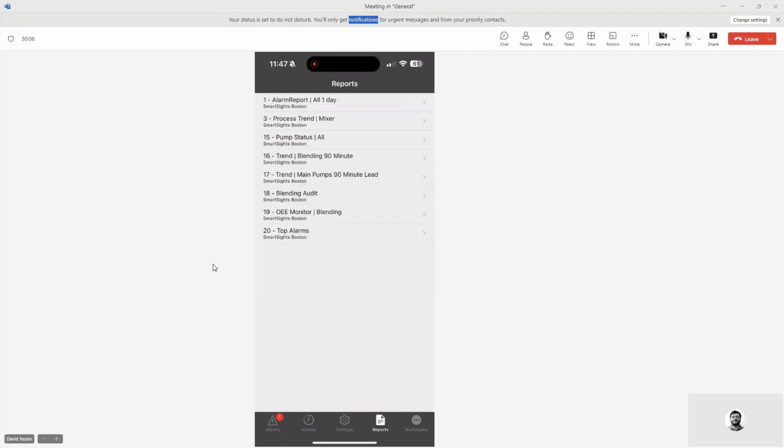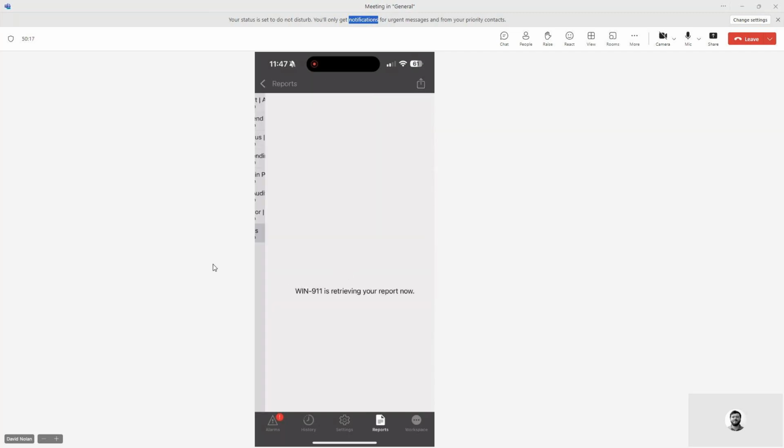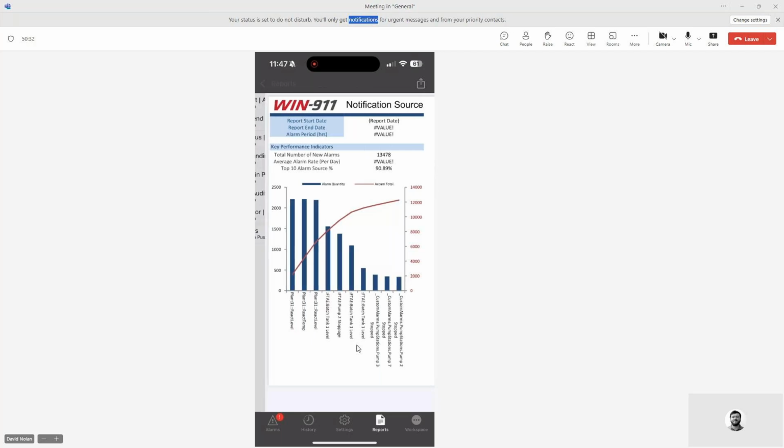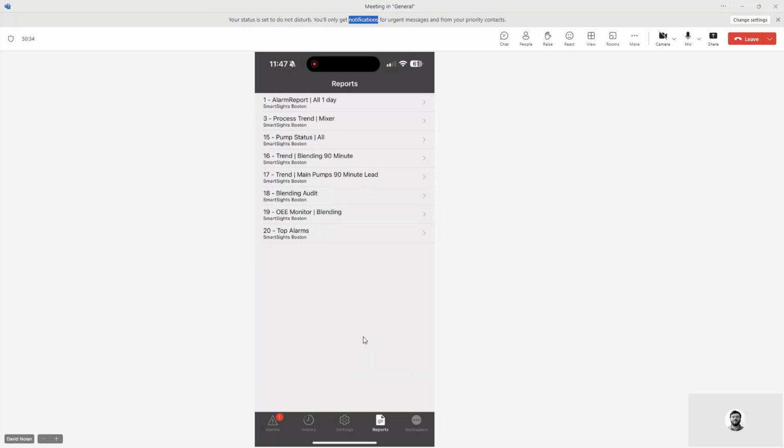And so these reports have maybe two different contexts in which they could be used. They can be used for proactive monitoring of the process. We can monitor how many process alarms we've experienced over the course of the week from different process areas, so we can see what the level of chaos or deviation is. We can also use these reports as part of the diagnostic and response effort to an alarm.